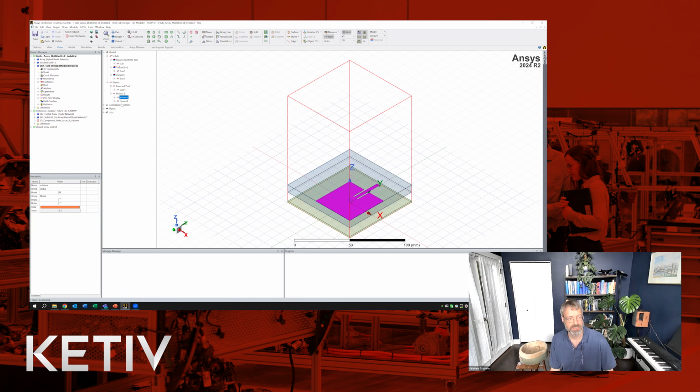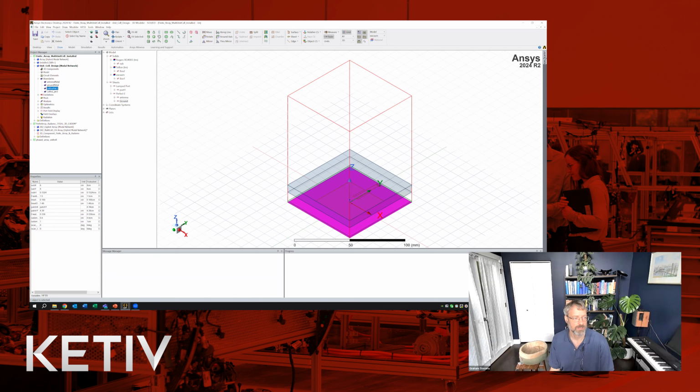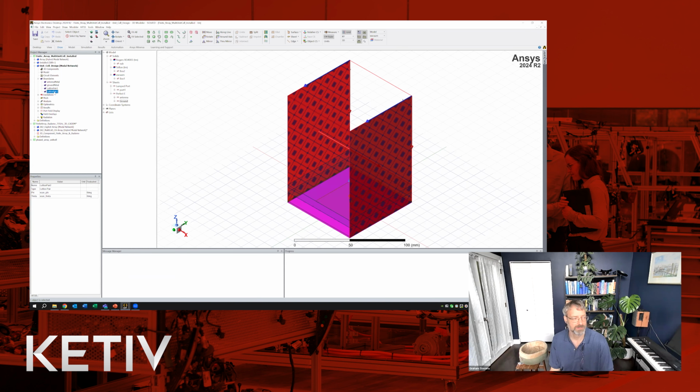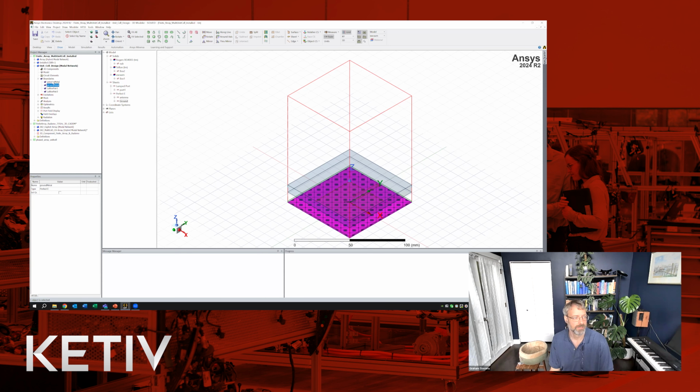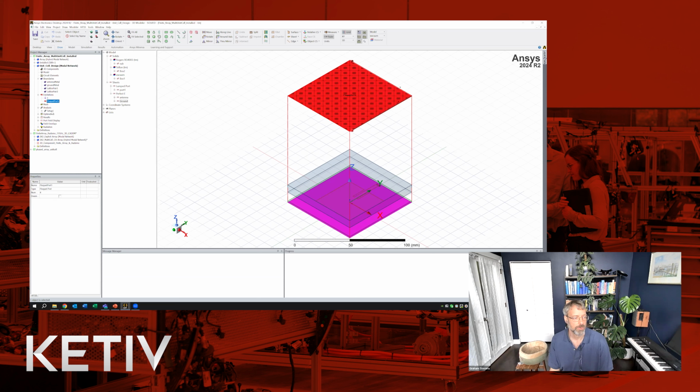It's just a patch antenna with a ground underneath it. Similarly, we start by setting up the lattice pairs, specifying any PEC or ground metal, specifying our input and our Floquet port, and we can run it, taking this as our initial patch.